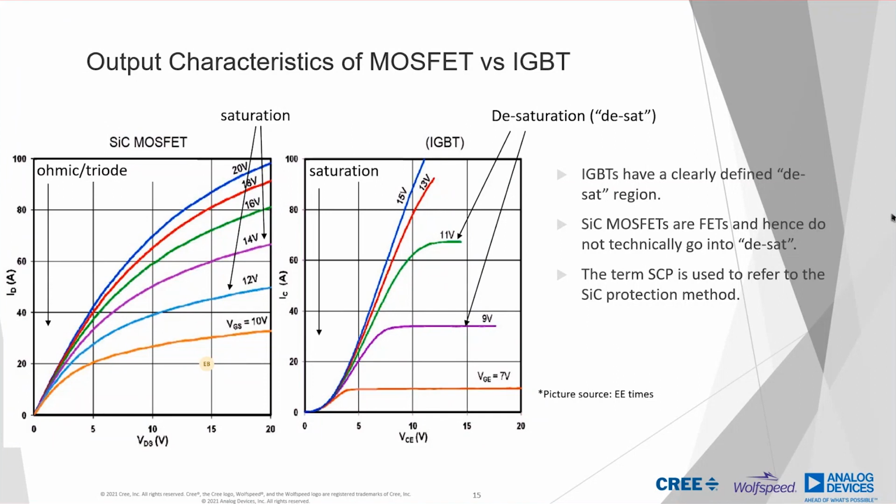With an IGBT, it's feasible to have a desaturation detection circuit that can detect and react to overload conditions as well as larger fault conditions. For silicon carbide MOSFETs, we believe the expectation should be focusing on protecting against the larger fault conditions using the gate driver protection, and then using the control system with the fast control loop to detect and handle overload conditions.